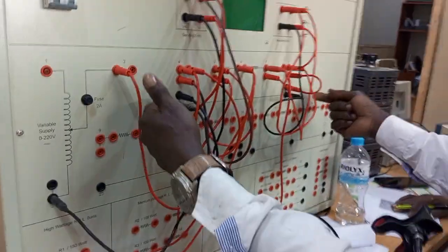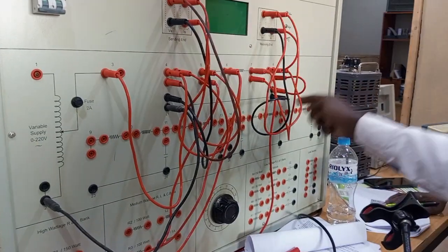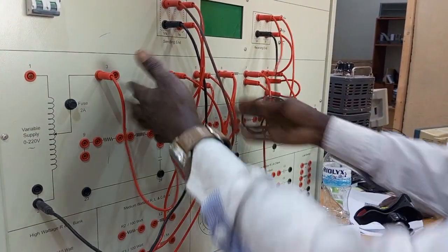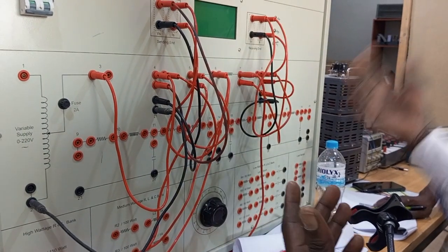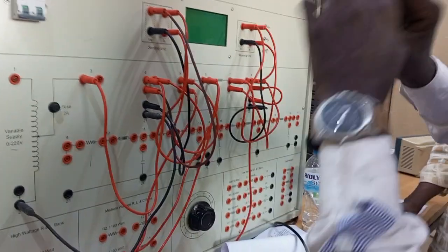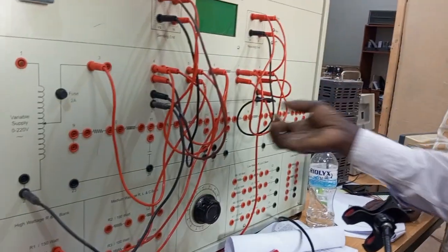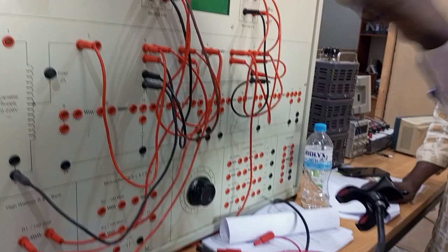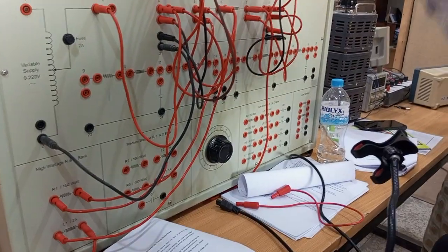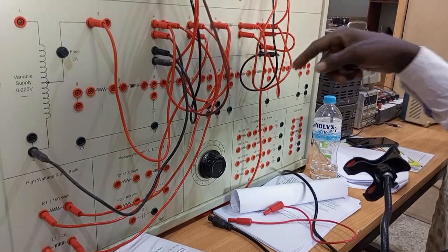What it's saying is that after we have connected this, whatever experiment we want to perform on short circuit, we should not let it be long. That's why we're having low voltage, because as it gets long, because we're having high current, the components used there will be warmed up. It will be heated up, and when it gets to a certain size it will melt, whereby it will not be able to work with the current supplied again, because it is high.